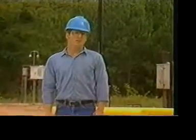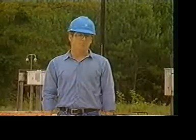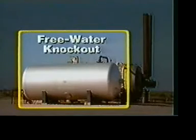Finally, mechanical devices such as gun barrels and free water knockouts are used to treat emulsions. A gun barrel is a settling tank which separates oil and water in the field. After the emulsion has been heated and treated with chemicals, it's pumped to the gun barrel where water and oil settle out by gravity. Gun barrels are still common, especially in older fields, but they're frequently replaced by heater treaters.